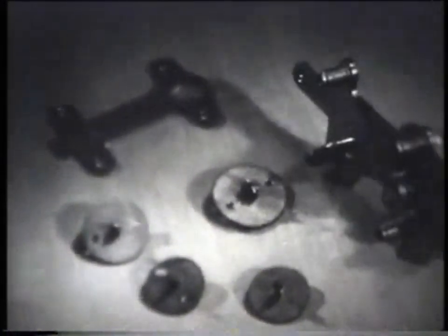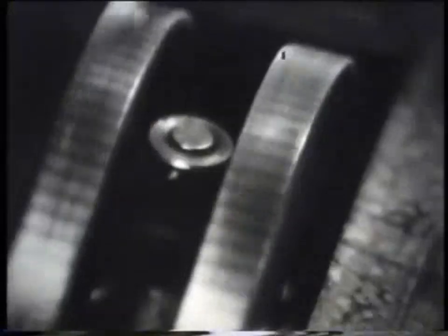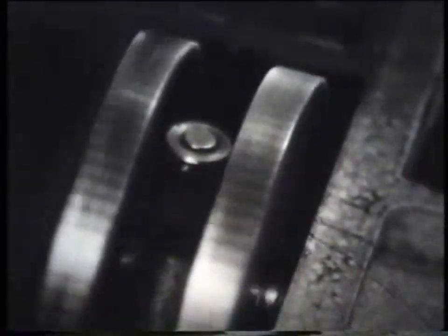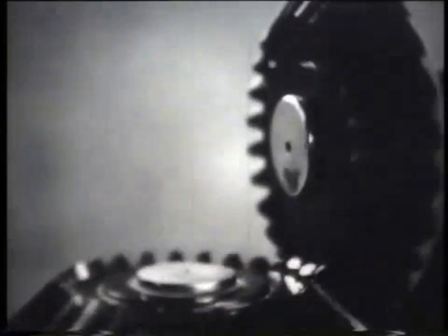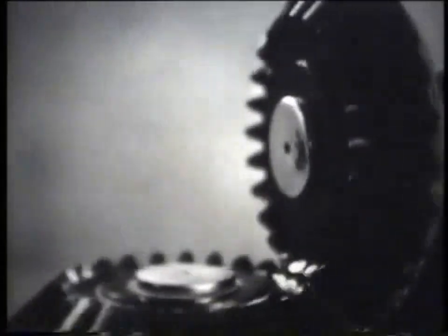Links of gear mechanisms are gears of various shapes and purposes. Cylindrical gears are the most common, forming teeth of straight-toothed wheels parallel to the axis of their rotation. In a bevel-toothed gear wheel, the teeth are inclined to the axis of its rotation. To transmit motion in space, conical gears with helical or straight teeth are used. The teeth of these wheels are cut on the surface of a round truncated cone.